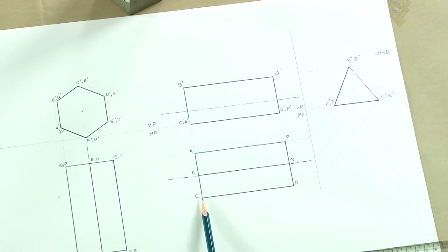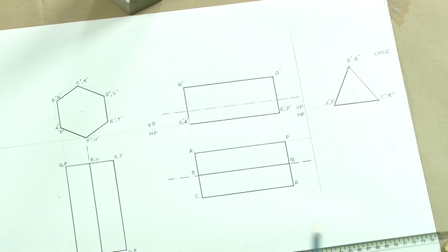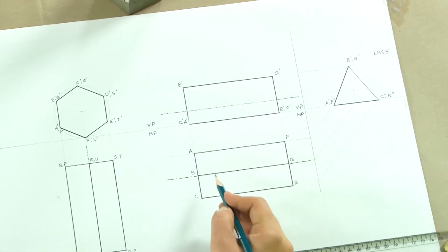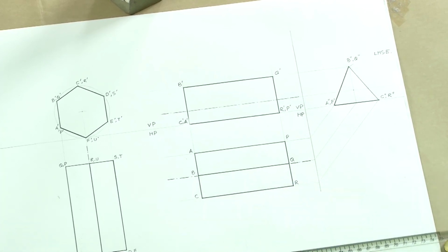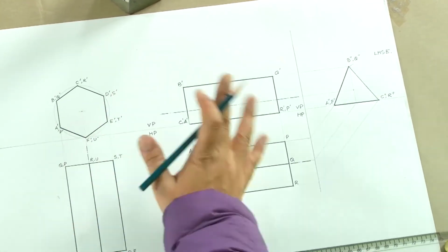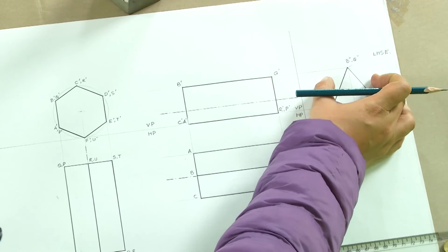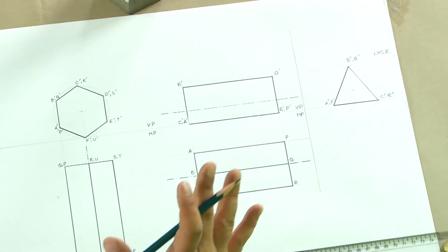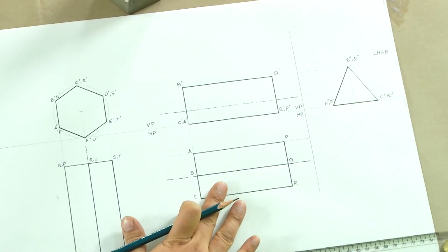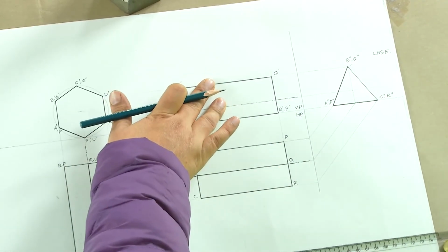We could have drawn it directly here, but that would have been a derivation, not a drawing derivation, where we could have just drawn the full size of the base and then just divided it, because that is what we know as a general geometric understanding. So we could have done that, but we should always avoid it, and we should start from the plane where we are seeing the true shape, the true dimension. So we started from this triangle, came back to HP, and then went on to VP.